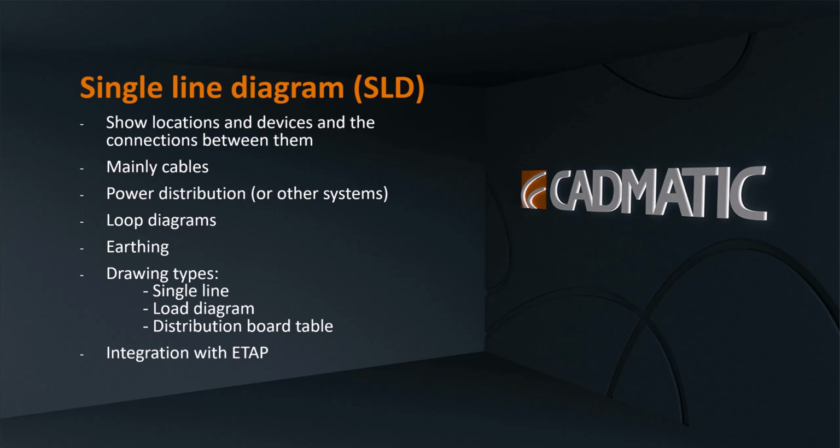You can do those in ETAP, and after you have done your simulations and you are happy with those results, maybe then you can import the ETAP calculations back to Electrical, and then you will have all the values, and maybe you need to change these cable diameters or the whole cable material from aluminium to copper or something else.